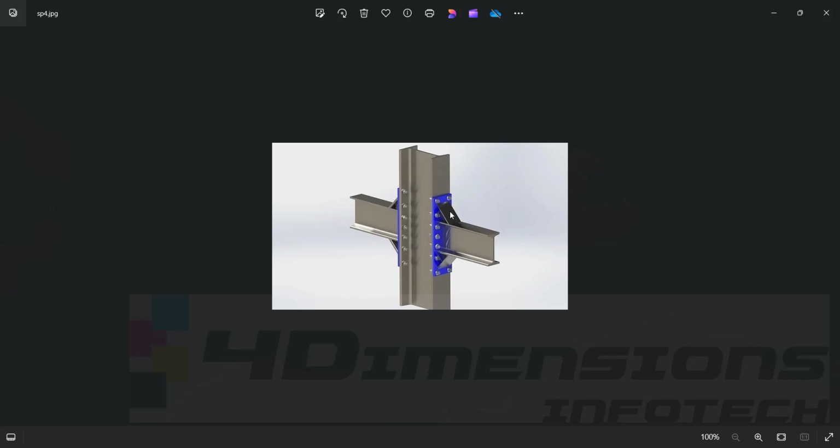For the support, ribs have been added here that are called gussets. We are going to see that also here. And then they are bolted on the structure. So this kind of structure we are going to make in weldments. The reason we are pronouncing it as weldments is because we are going to weld one structure upon another. So we'll start with the sketch here.